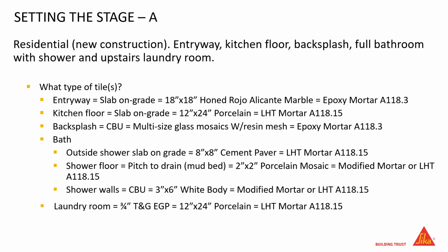We're going to the high performance mortar that we're using in this. We've got our non-slump category to it, so that way we can really use that 1/2-inch trowel for those tight grout joints that these customers now want these days. And it's going to have the body to hold that material without shrinkage. We're able to adjust our lippage on these and have a beautiful installation.